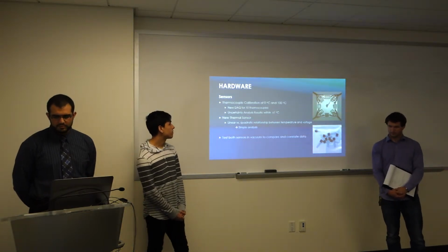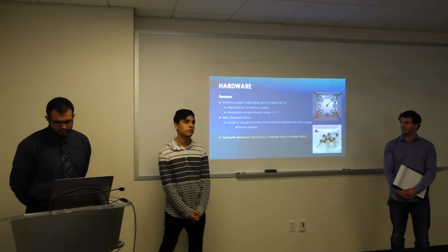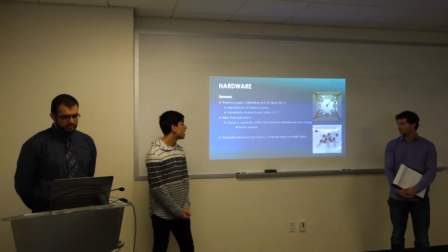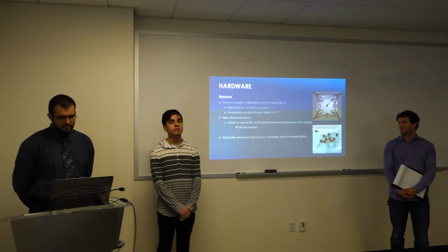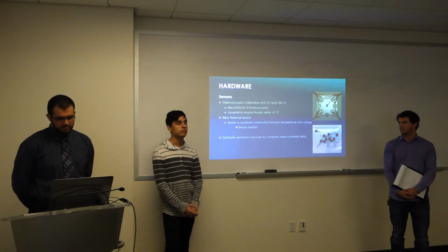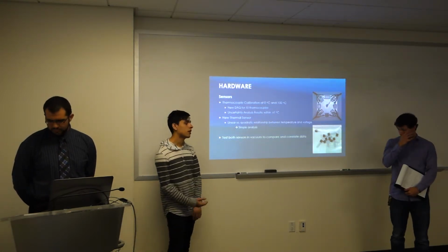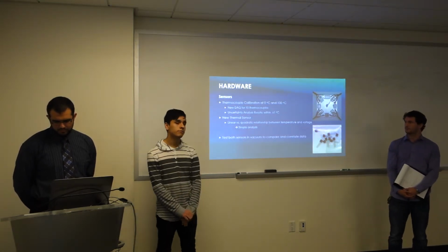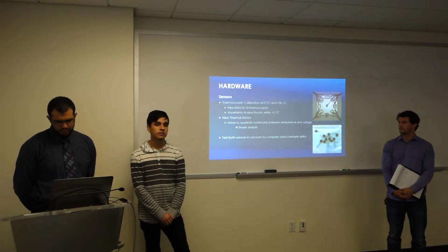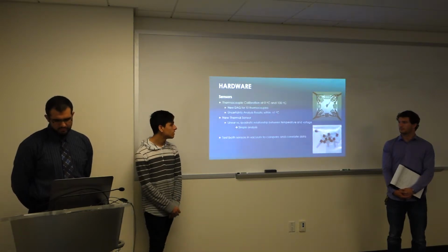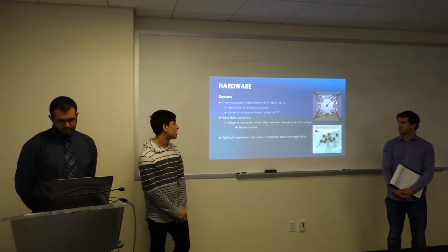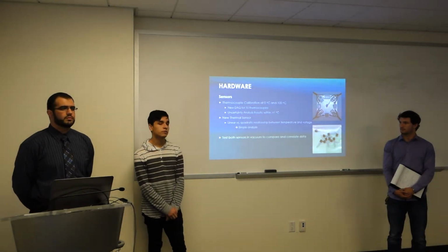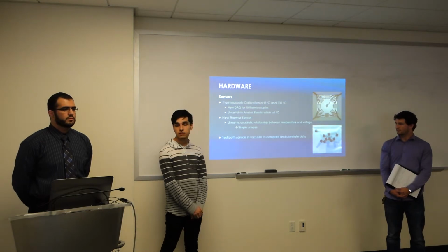And so for our next test plate, we will be using a new sensor, which is pictured up right there. The major benefit of this new sensor is that the analysis is much simpler. Instead of a quadratic relationship between temperature and voltage, it's linear. So it'll be much quicker and simpler to analyze the voltages given off. And in our next test plate, we're going to actually use both and then compare the data.